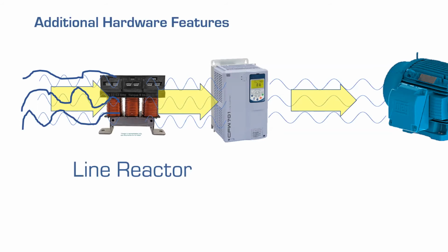Adrian, the same NEMA ratings would occur here that we'd have to be careful about? Line reactors, some higher end drives come with them built inside, but usually they're external and they would be inside a NEMA enclosure. Yeah, okay. This one that you're looking at now, that's an open style one. So you would always have that either inside a control panel or inside its own enclosure.